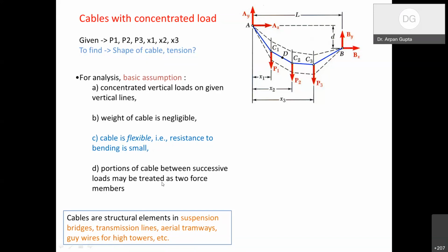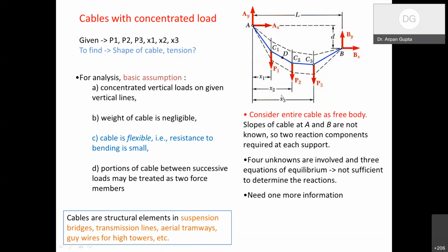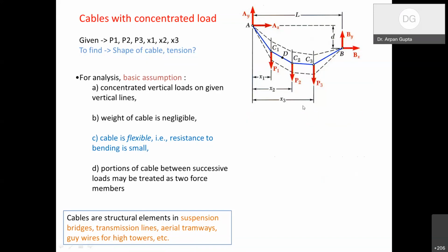And the portion of cable between successive loads may be treated as a two-force member. Since we are neglecting the weight of the cable, let's say between C1 and C2, we will consider it as a two-force member, right? So now if we consider the first analysis,